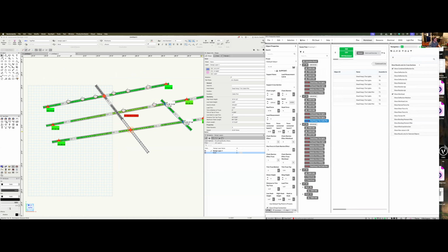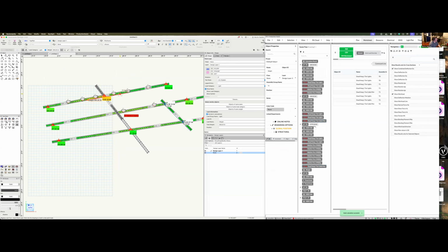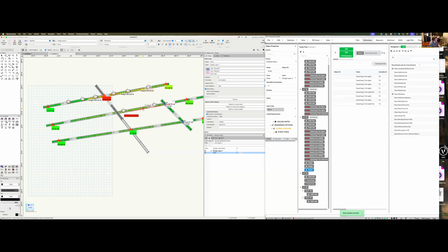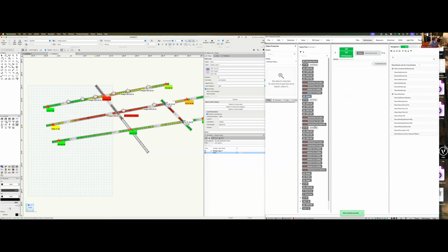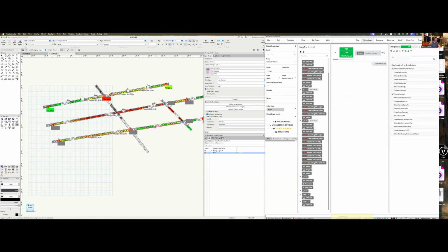It's crucial to interpret these results correctly. The calculations assume a properly rigged system, so any misleveling can have significant consequences. Production Assist visually highlights overloaded hoists with a color-coded gradient, so you always know when a hoist is nearing its capacity. Always compare the calculated values with your expected design parameters and verify them using load measurement cells if needed.